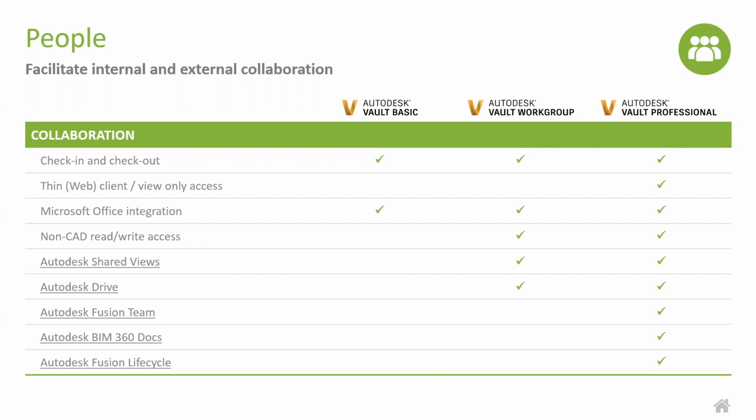For example, an AutoCAD file with some XREFs and some PDM systems will never connect together. So all those links could be broken forever. Absolutely. And I've seen that happen a couple of times. Yeah. It's like, why do I have to resolve the links every time I open the file? It's exactly that. The PDM system is not aware that there are links.